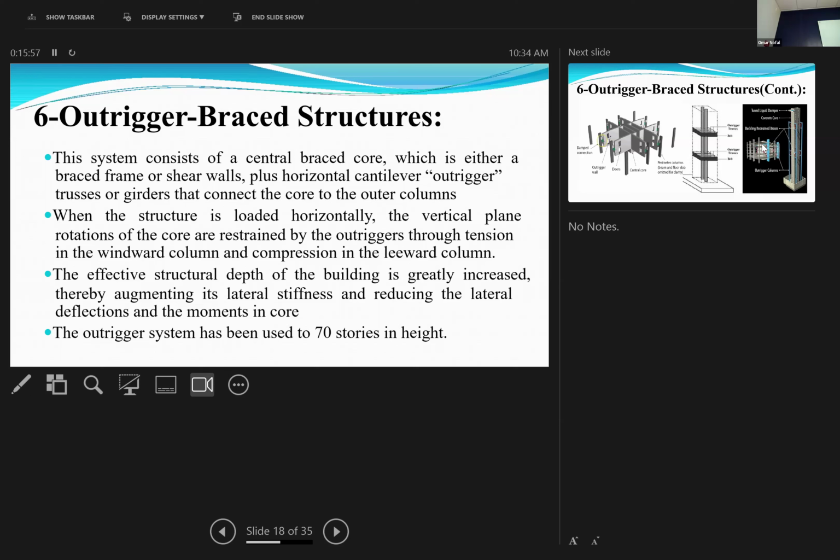Can you imagine if the length of your building is 60 meters, you make a 60-meter-long beam from the first column to the last column, and it has to be connected with the shear wall. And it needs to be connected with the columns at the end, all the columns that it meets. Basically this system works like this. This is the outrigger, which is the deep beam, and this is the base, and you have a column, for example, at the end, and a column at the start.